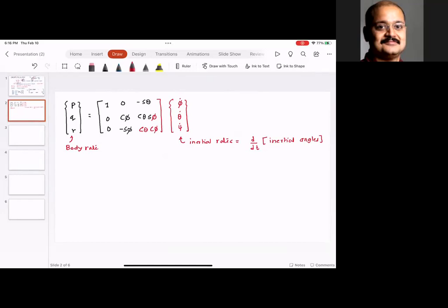If you integrate those 12 equations of motion numerically, you are going to get results which would look weird. But that is the case, because the quadcopter is an inherently unstable system. Unless you have a control input, you cannot keep the quadcopter in a controlled state.